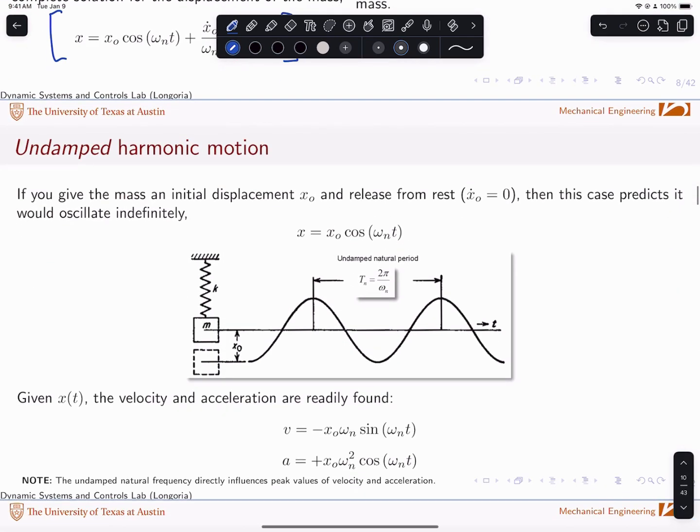So, for example, here's a case: you have a mass spring system, you deflect it and let it go, and it's going to oscillate. We used to do real quick experiments this way, with a very lightly damped system. If you release it at x naught, it's going to oscillate, and you always know what that displacement is. But let's say you have an accelerometer on here and you're not measuring displacement.